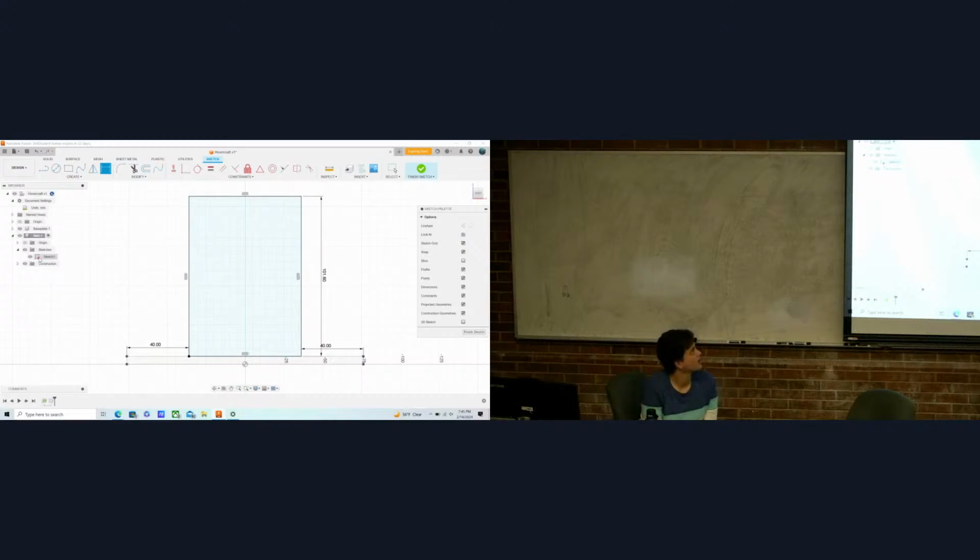We need to go around, and then go forward. And then you do the same thing for the other side. And now make it so the wall is always 40 millimeters from the outer edge of this. If you click once and you haven't clicked something else, it's thinking you're just trying to change the height of that wall. It's telling you it's so constrained because the height's already been set by another dimension. So you might want to zoom out so you can see the other side.